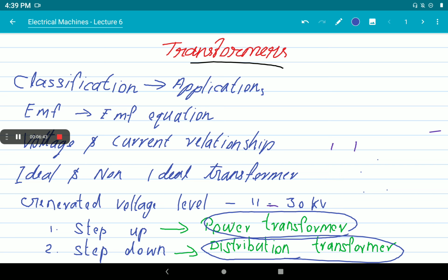Okay. So in railways, we are using DC series motors to drive the electric engine. And in new systems, we usually use induction motors. So we converted that into AC itself. At that time we use a single phase transmission system, so single phase transformers are used in railways also. Then AC is transmitted, which is converted into DC and drives the DC series motor, which then drives the electric vehicle. That is the basic working of an electric train.